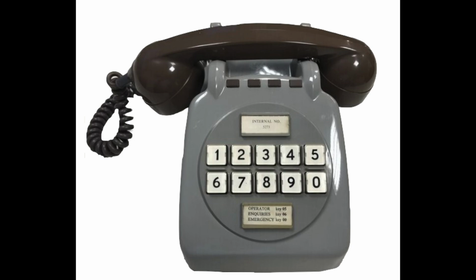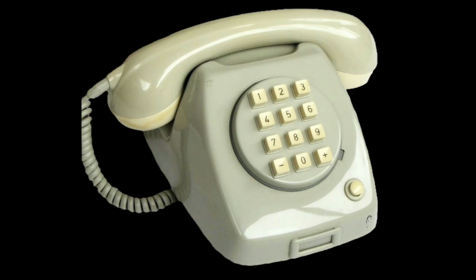These telephones can only be used in combination with a suitable telephone exchange or PABX, as they are called in the UK. The signaling makes use of the earth wire in the local telephone network. By switching the polarity between the A and B wires of the line and the earth wire, the exchange can work out which key is being pressed. The keypad circuit is passive and uses only diodes and resistors.